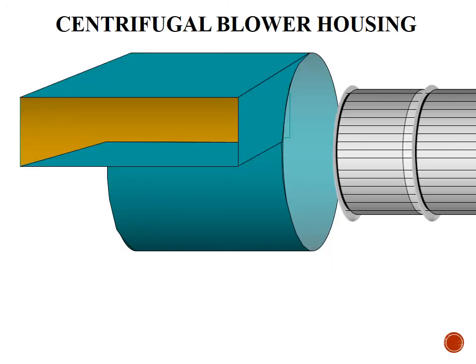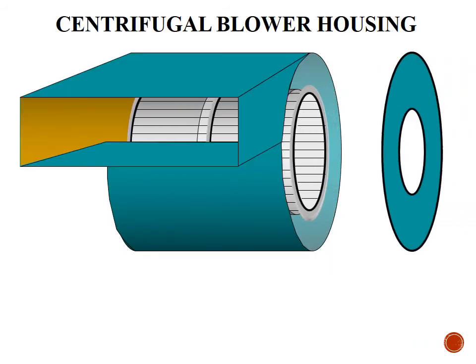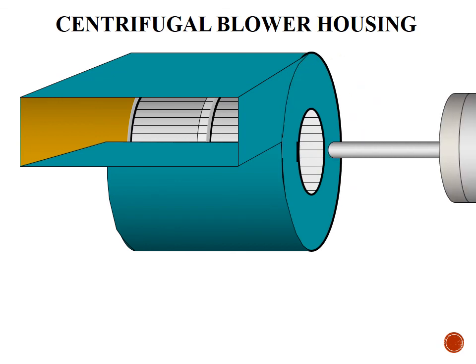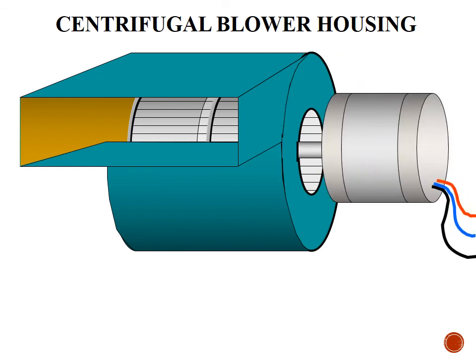We can also have squirrel cage fans go inside the duct along with the motor, and probably you did that in the refrigeration course when you replaced the fan. You can see how it is a little bit inconvenient, but we need those fans to act like pumps to push the air around the duct.